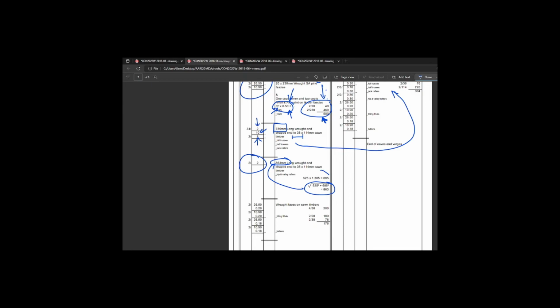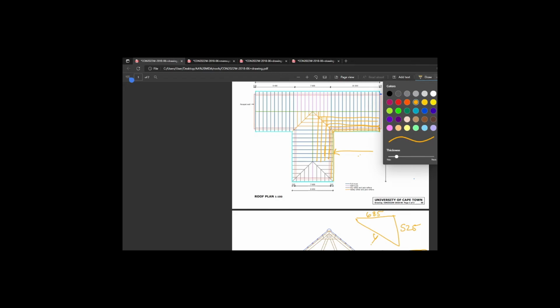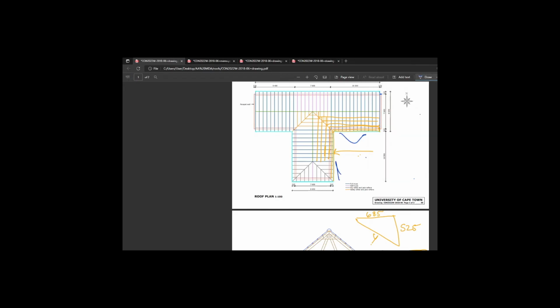Wall face on sawn timbers. This is just a value of all the exposed, what we call it, supportive members of your tiles. And I don't mean trusses. We have smaller battens now running across like this. Sorry, they're going to meet there at that 45 and change direction, right? So what we want to know is which pieces of timber will be visible to the world, and how do we treat this timber. If you are lazy, you might leave it and say there's nothing wrong with it. No one's going to see it, I don't mind, maybe there's bushes and trees here, who knows.